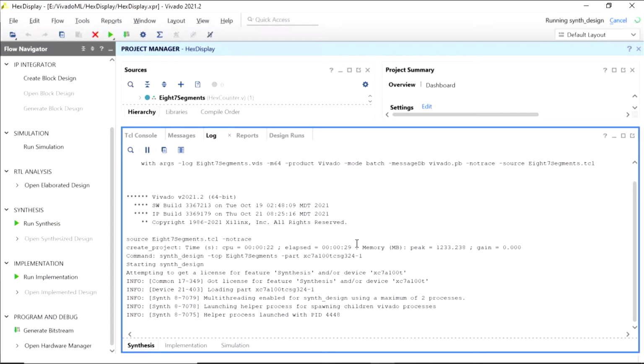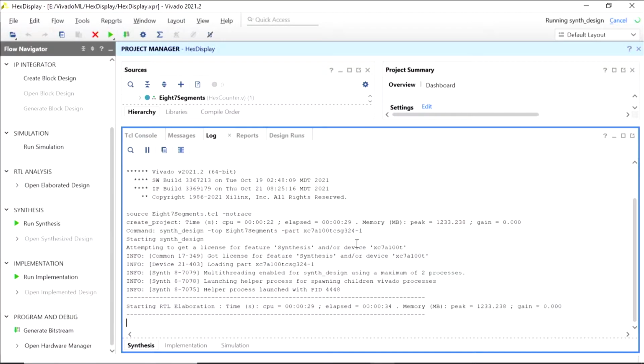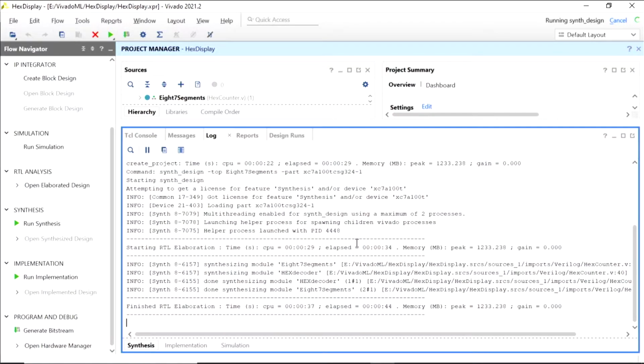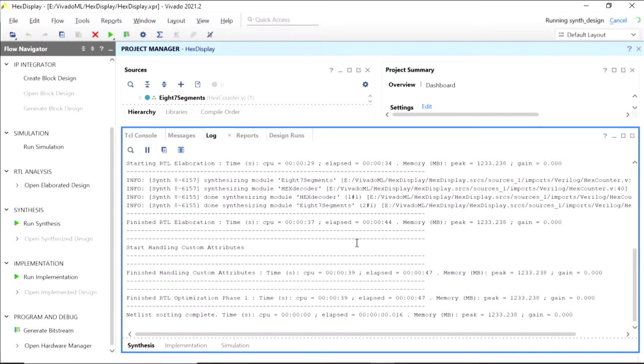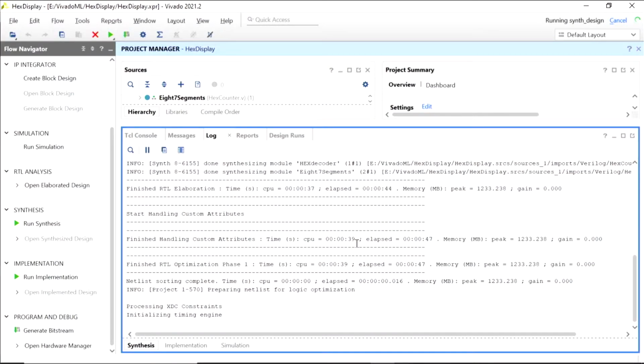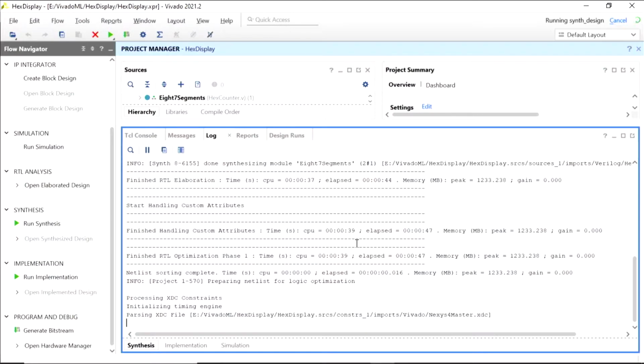It's not too much trouble, but sometimes you have to exit Vivado before you can do that, because a lot of the files kind of lock it up from deletion. They lock out deleting the files because the document is open in Vivado, but nowhere else. And you gotta close out, or at least get to the main intro screen with the menus, and delete all the sub files.